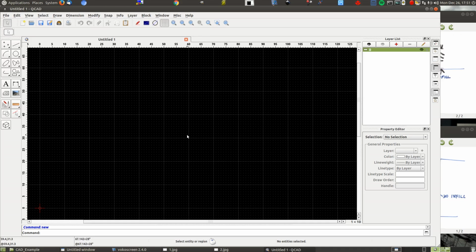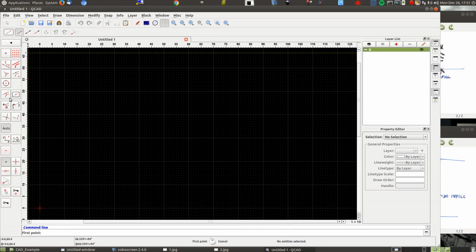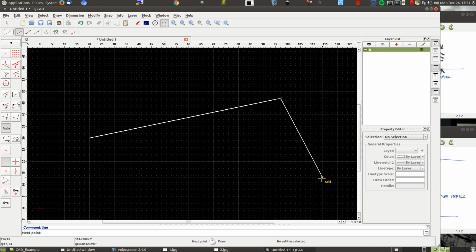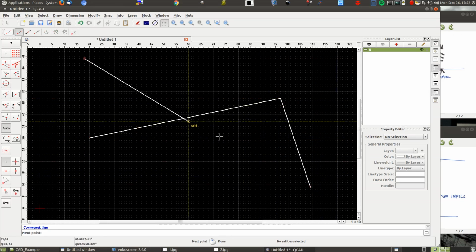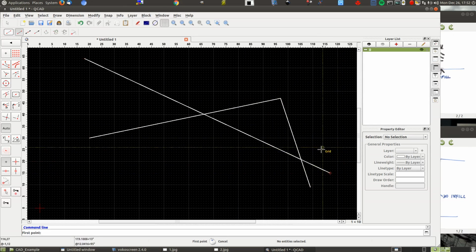There's a few features. One that I particularly go for is if you go to draw a line, let's just draw a line. The snap tools are quite smart. Let's say there's one line. If I want to pick this point, it'll pick the intersection. If I draw another line like that, it'll also pick the intersection. It should also pick a midpoint on the line. So its snap is what you call auto snap. See this auto snap function. In LibreCAD, you have to pick these snaps, or maybe they've changed that functionality since I last tried it. In any case, I'll show you how to get LibreCAD.